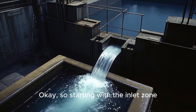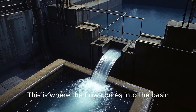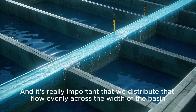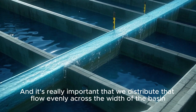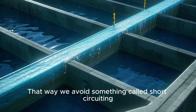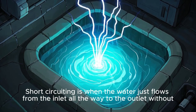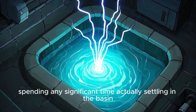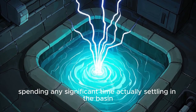Okay, so starting with the inlet zone. This is where the flow comes into the basin, and it's really important that we distribute that flow evenly across the width of the basin. That way we avoid something called short-circuiting. Short-circuiting is when the water just flows from the inlet all the way to the outlet without spending any significant time actually settling in the basin.